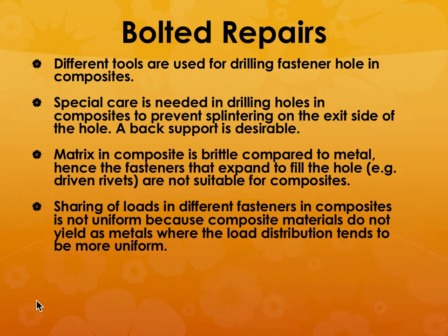And the other thing to note is that the way the fasteners will behave under some kind of a stress is going to be different from metals. So the load distribution is not going to be uniform between the composite structure and the bolt material.